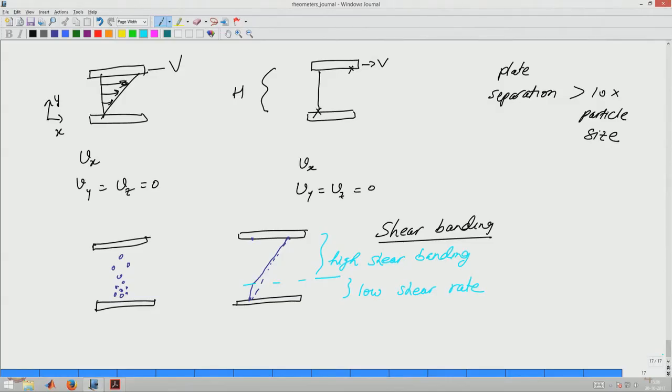One may therefore argue that for such materials you should not really measure properties, because settling is a very significant feature, right. But for settling slurries, if we need some estimate of properties, then we must do such experiments, but we have to be careful that while analyzing our data we must know that the overall flow is not really what is assumed, which is a linear velocity profile.